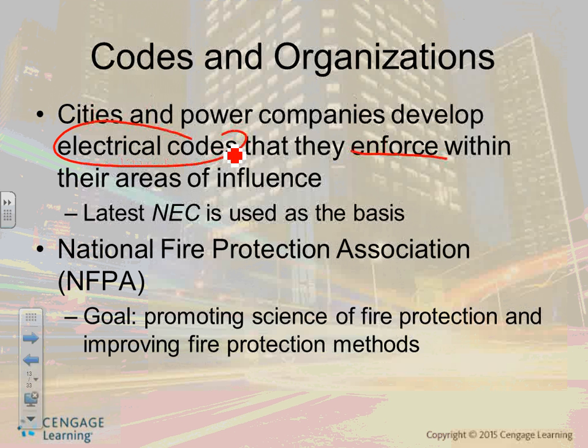You come to Bloomington, for example, or my city, and when you do lighting outside, my God, they drill you. Has anybody done outside parking lot lighting in Bloomington? Yeah, the inspector will come with a light meter and literally measure it. And if it doesn't achieve the requirement that they have, they don't want light spill because the neighbors complain, they will make you redesign the place. So it's a big deal. And you are to submit the outside lighting to the city of Bloomington. They have to approve it for you before you do it. And when it's done, they go measure it too.